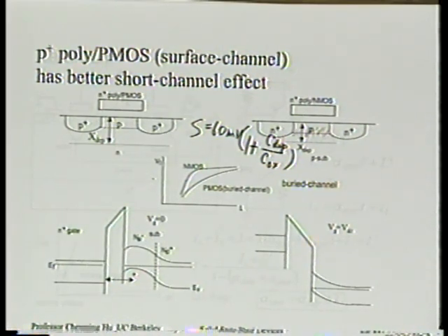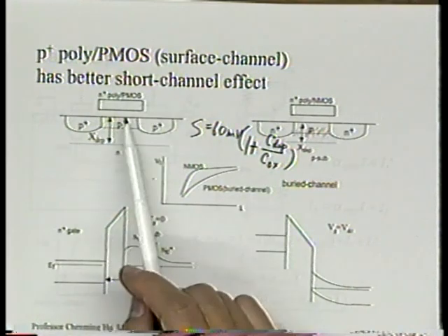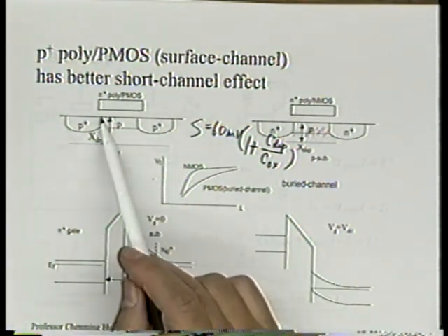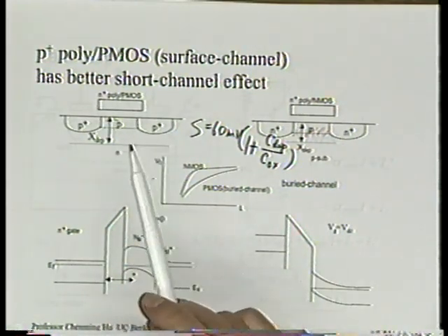Is that because of the boron doping? Very good, the leakage? Yeah. I think in homework you were asked to look into this question. A buried channel transistor in the strong inversion case, when the VG is large, actually you can show holes still cling to the surface, flow at the surface.